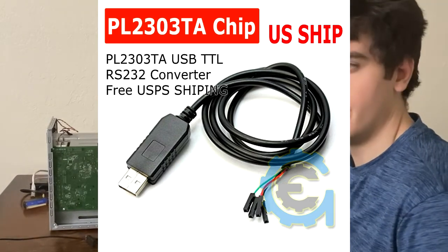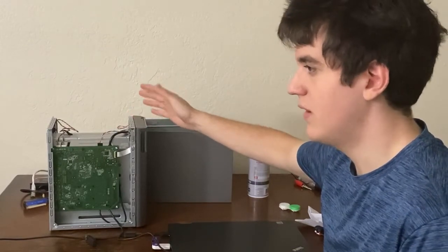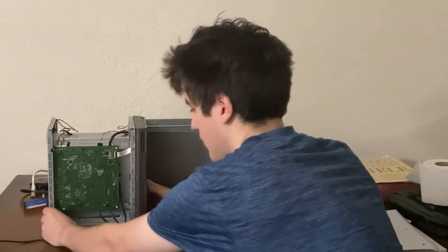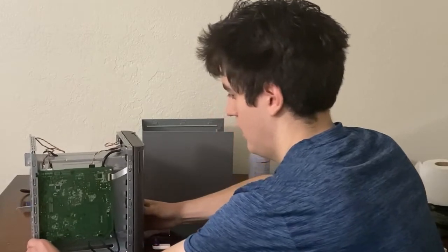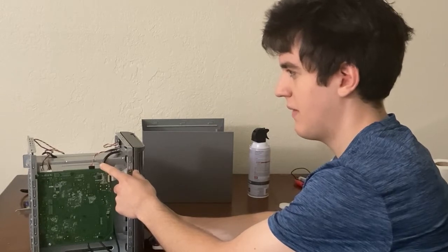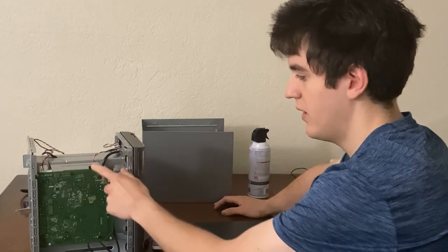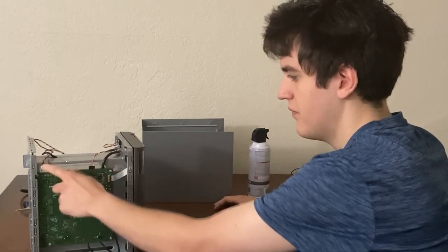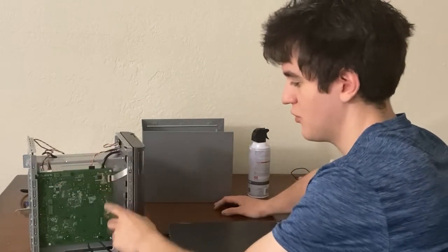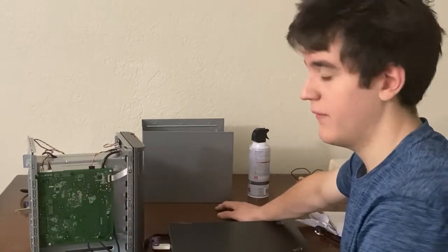You're going to need to remove the computer cage, the PCI, or technically, SATA card. You're going to just need to unhook that. Yeah, you're gonna need to unhook this, I think it's the ROM recovery USB, this ribbon cable to the screen, the power to the screen, and 2 other data lines. But you need to unhook those, unscrew 1, 2, 3, 4 screws, and then you take the motherboard off.